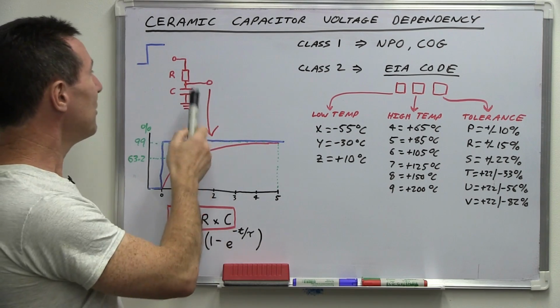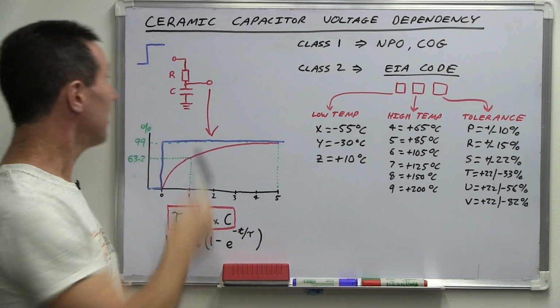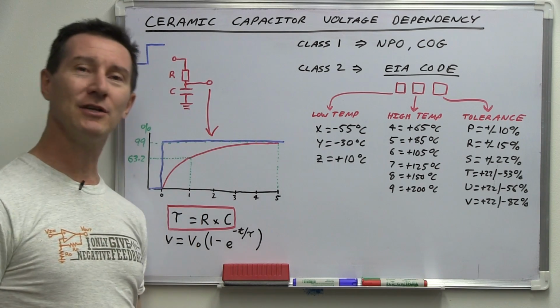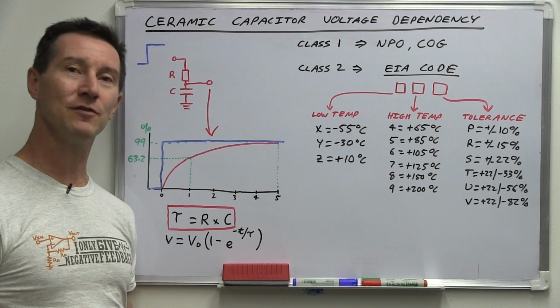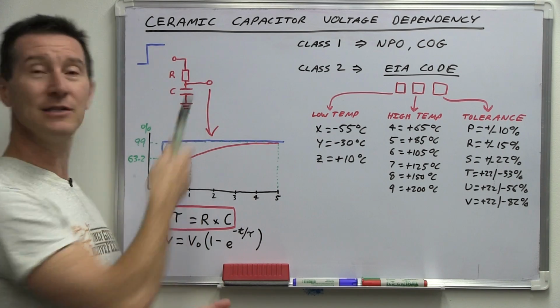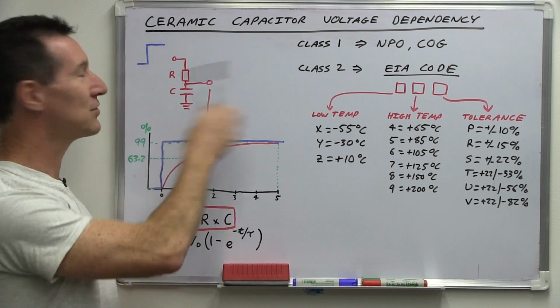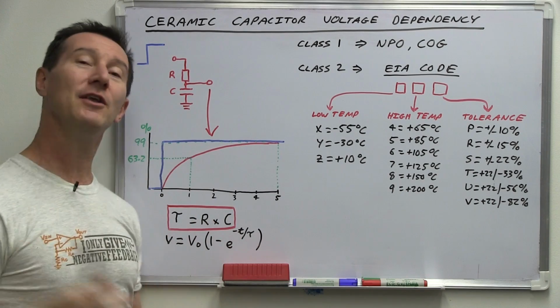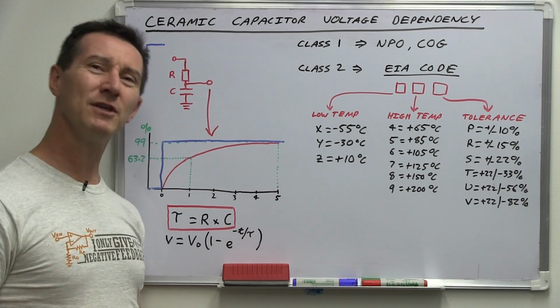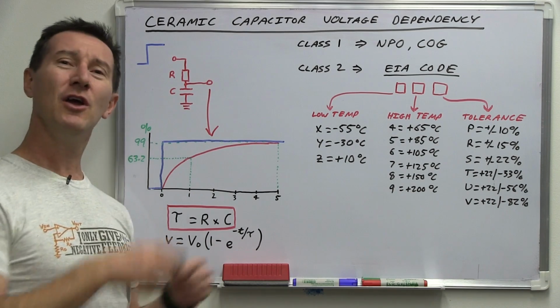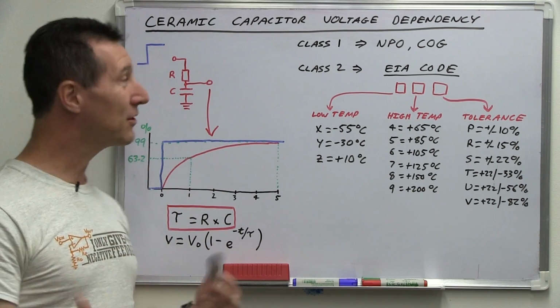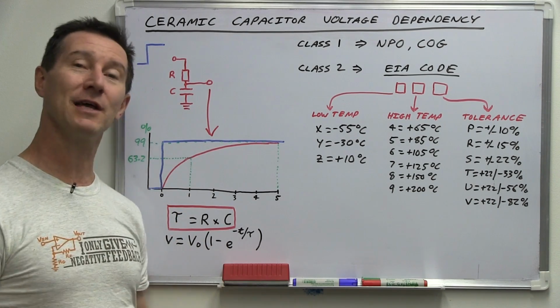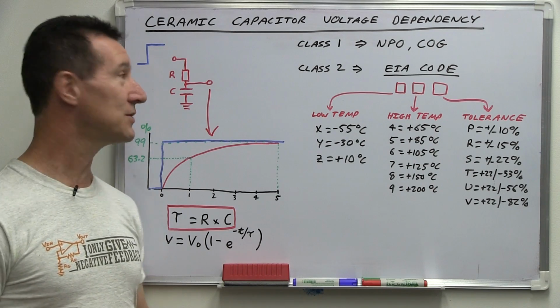But a capacitor. Right, simple RC charge circuit like this, very common application for capacitors. RC time constant, charges up, gets to a certain threshold and you can detect that and you can use them as timers. Very typical application, not that accurate because, as we're aware, capacitors are not particularly high tolerance devices.